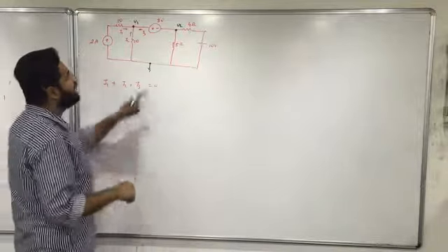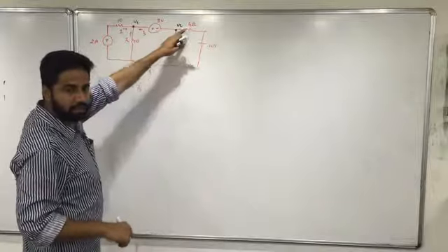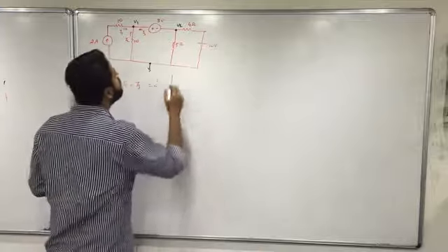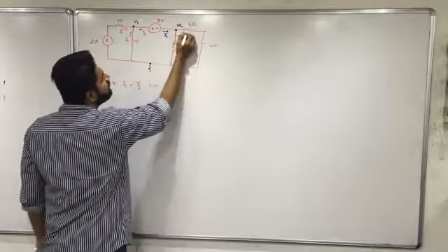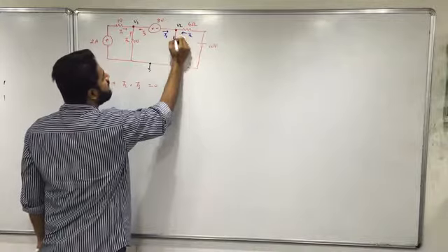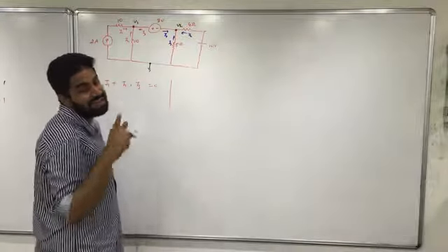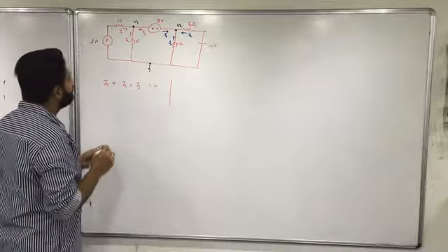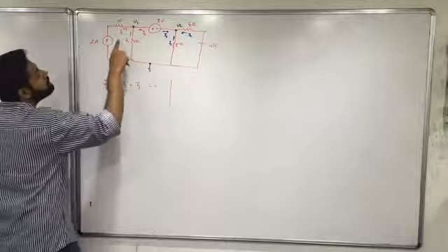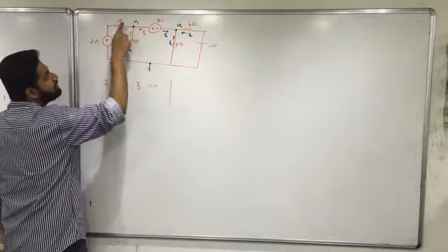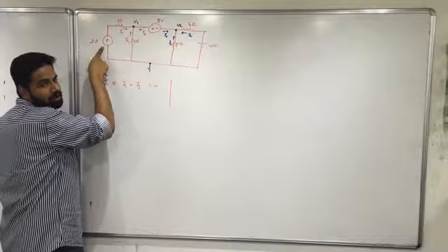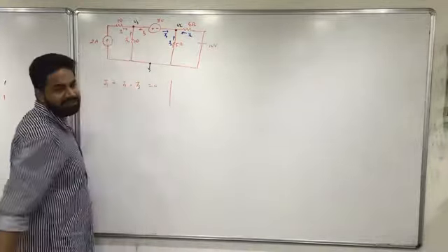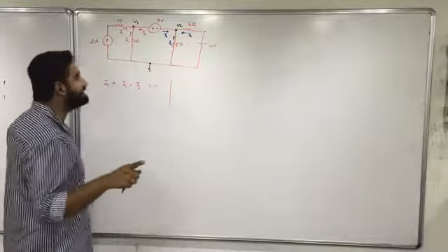Fine. And here also we can make another equation. So let's say that equation is like this. We'll do it with blue. So we are having this I1, this is I2, and this is I3. Again, you can take any direction you wish. Fine. Okay. So let's write down what it signifies. So 2 ampere current is coming over here. This resistor is connected in series with this 2 ampere current source. So this becomes a redundant branch. Fine. So we will short circuit the resistor or we will neglect the resistor. That is the very first thing that we will do.